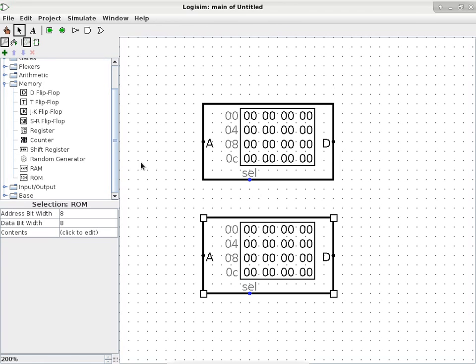Okay. And we can change the address bus by changing that. You are basically saying, okay, how many locations do we have in this particular memory chip? The default is 8. In other words, we have 8 bits to specify which location we want to access. So how many locations are we talking about, given we have 8 bits to specify a location on the chip? 256. 256 is correct, because 2 to the power of 8 is 256.